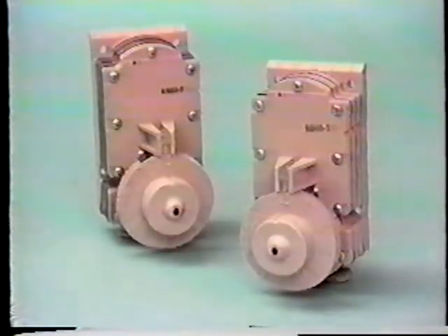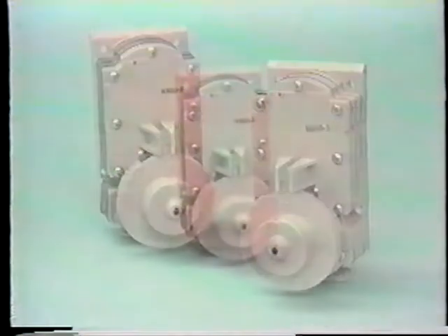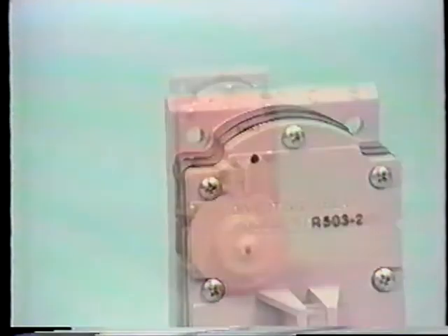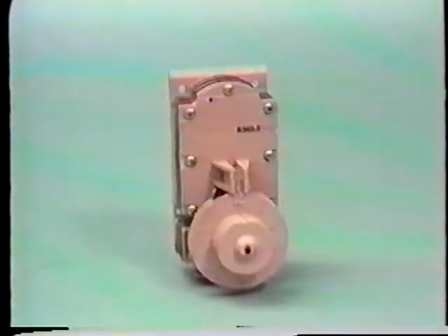The first device to look at is the adjustable set point diverting relay, which comes in a single-pole double-throw model and has the option of selecting a 0.3 or 3 PSIG switching differential. For this device to function properly, it must have a main air supply of 15 to 25 PSIG piped to its M or main air port. The primary function of this device is to convert a proportional pneumatic signal into a positive switching action at some predetermined setting.